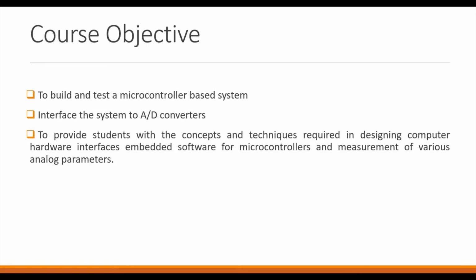Second, since those physical quantities will be in some different form, we as engineers have to convert them into an understandable quantity. If you have any electrical quantity, that will be in terms of voltage or current, but we understand the physical quantity. If you want to sense a temperature, or measure pressure or flow, these are non-electrical quantities. But we as electrical engineers will first sense it as an electrical quantity and then convert it into its original value. Okay, so for that we need a converter which will be an analog to digital.